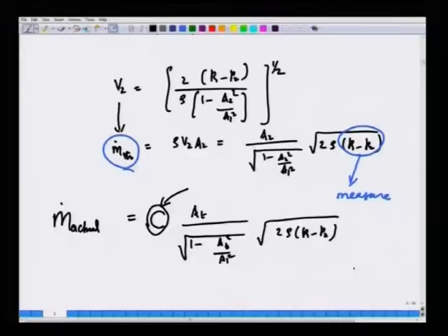That will give us a way to compute mass flow rate in a real application by simply measuring the pressure difference at an upstream point of the flow meter and at the downstream point of the flow meter. So, that is the idea of restriction flow meters. We also mentioned that this is just a generic discussion, and in practice there are orifice meters and venturi meters which all fall into this restriction flow meter class of flow measuring devices.